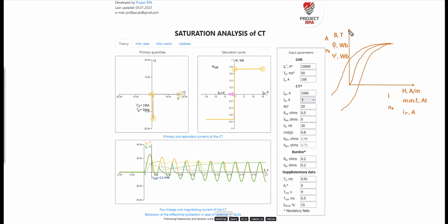The curve is usually shown in a BH diagram. Here we see an initial magnetization together with a hysteresis curve. It is surely all correct, but the practical approach has led to all this being gradually simplified. In the end, a rectangular magnetization curve emerged as the simplest type. However, these simplifications were not adopted without a reason. With certain assumptions, a rectangular magnetization curve can be trusted instead of this complicated curve.